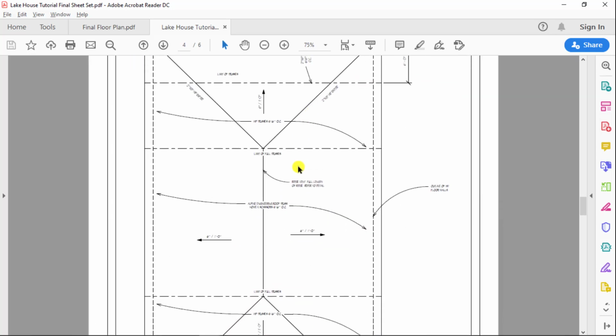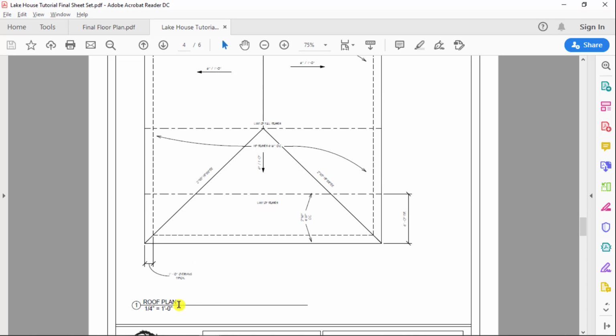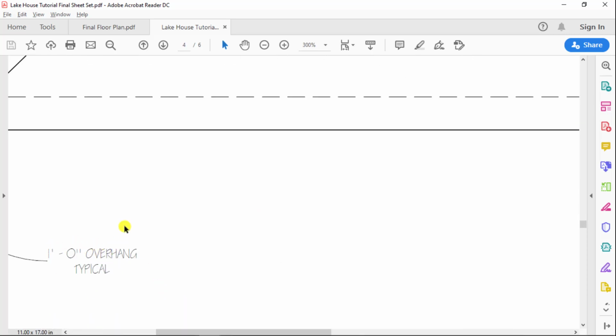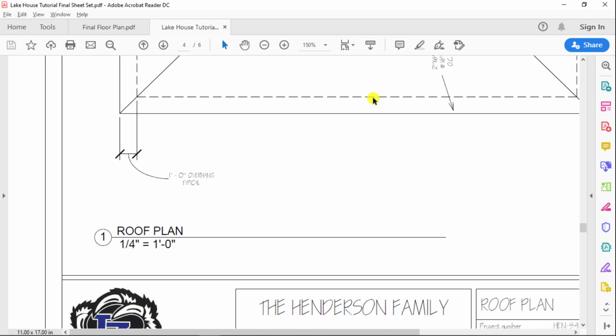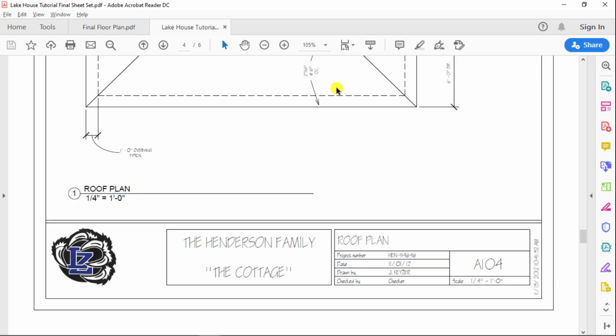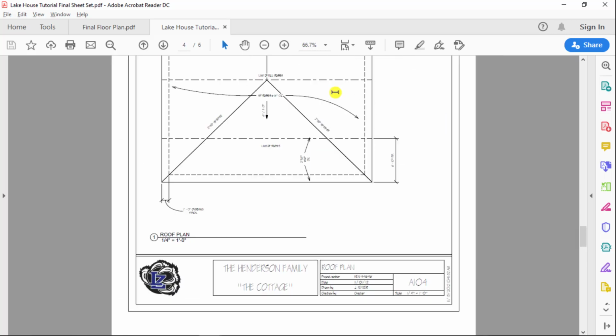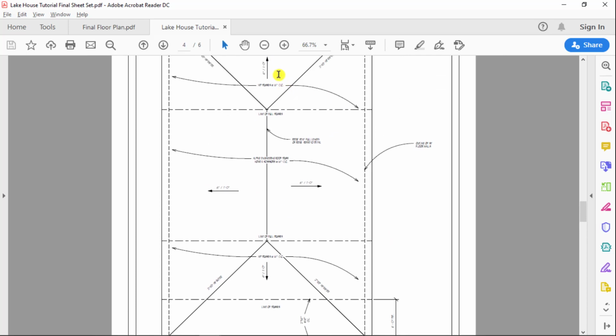So we see down here that we've got a foot of overhang for our roof, and that's how far the roof sticks out past the house. For this project, I want to change that to 2 feet. So we're going to use 2 feet for our sample house here. So the other thing we notice is that we've got 4 angled faces here. It's noted by these pitch symbols and which way the roof flows down. And this is what we call a hip roof.